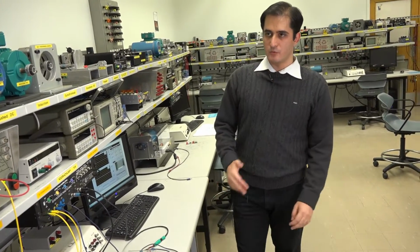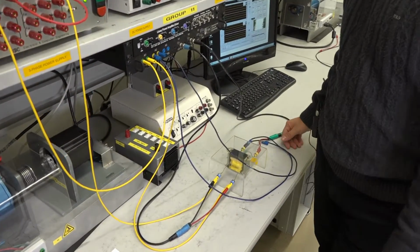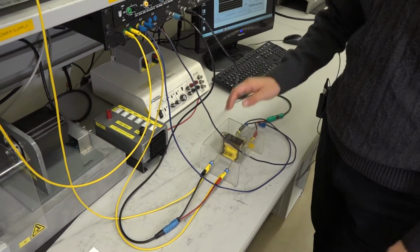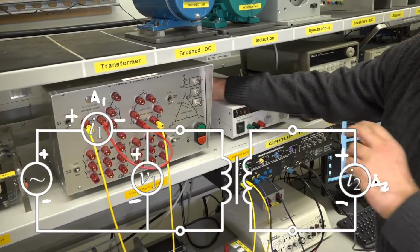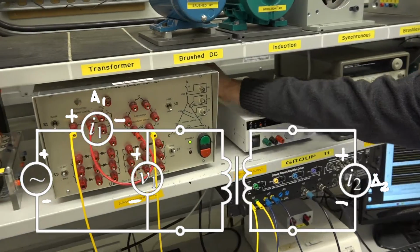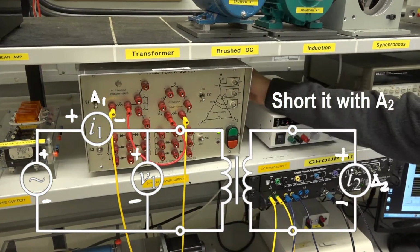So the next test is the short circuit test, and we need to do that to be able to calculate the transformer parameters. To do the short circuit test, first we need to turn the primary voltage all the way to 0 because we are going to short circuit the secondary side.